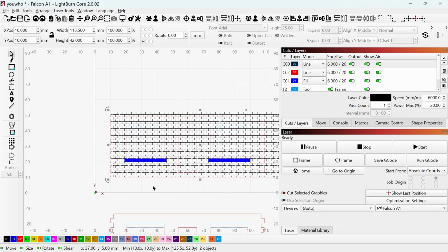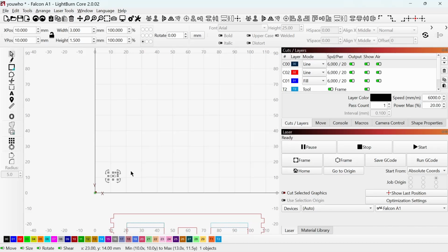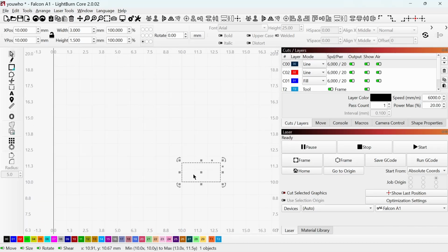So on this design as well, the lines are for my laser, the kerf is 0.04, so it's a very, very fine line, and there's not much mortar on top of it. So let's look at a way we can add a bit of mortar joint that's going to be more scale-like. We remove all this we've done beforehand, folks. Just Control Z, back to our brick. This is the little brick here.